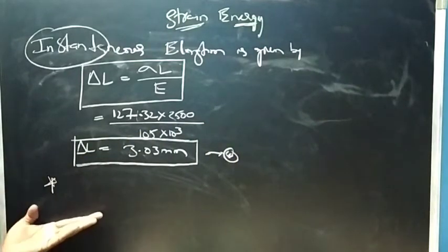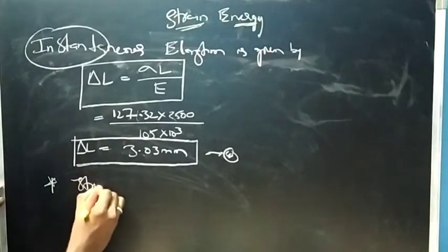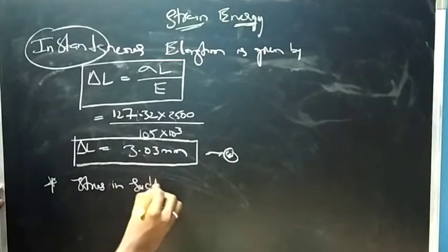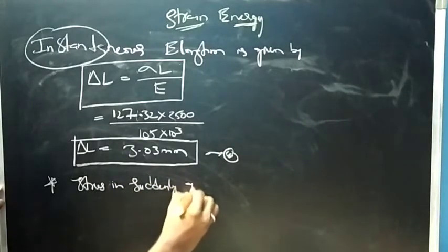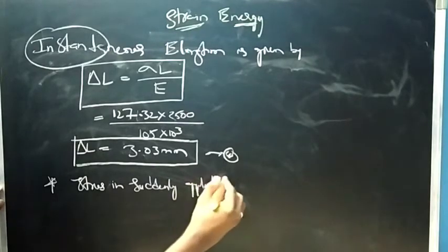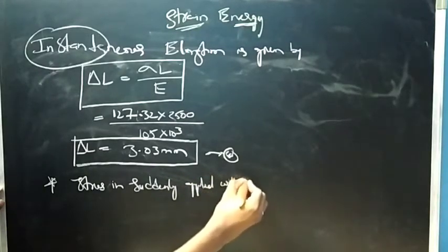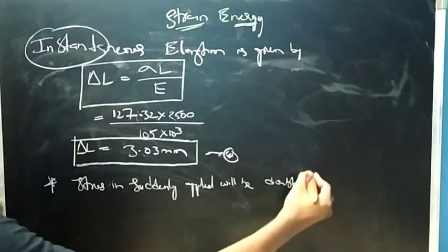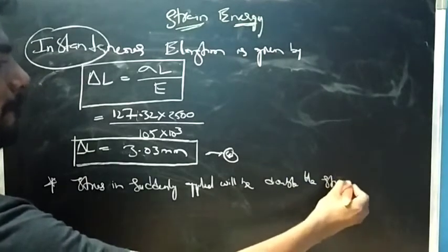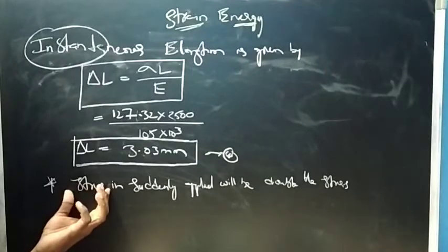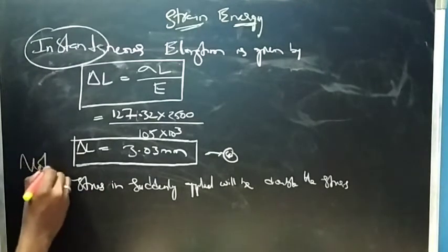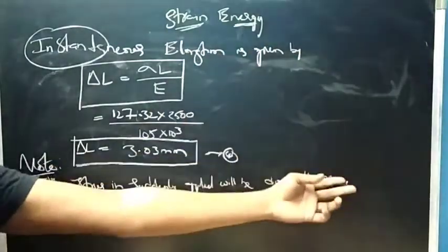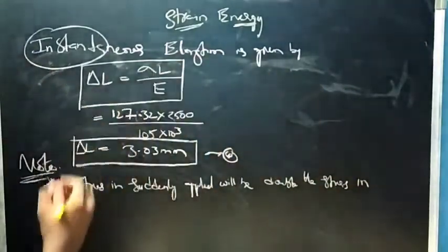So I will write here, you have to note this important point: the stress in suddenly applied load will be double the stress in gradually applied load.